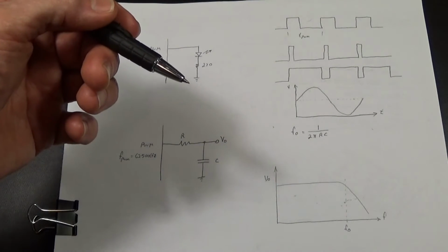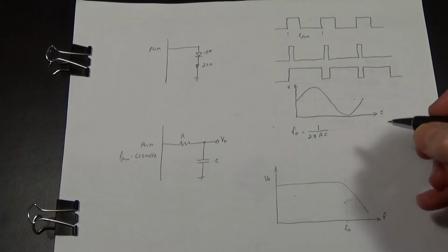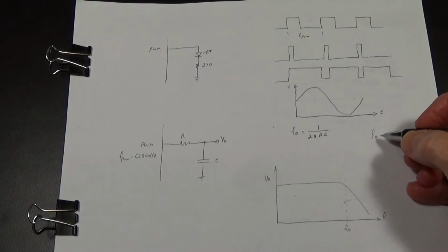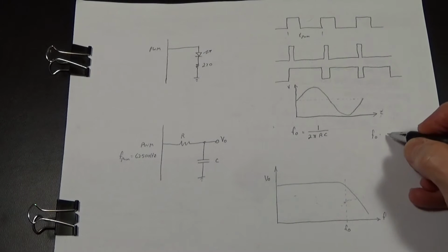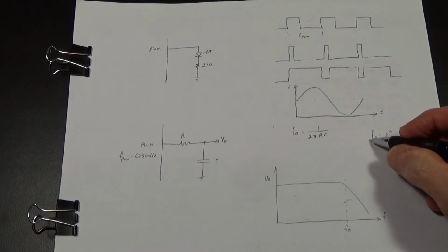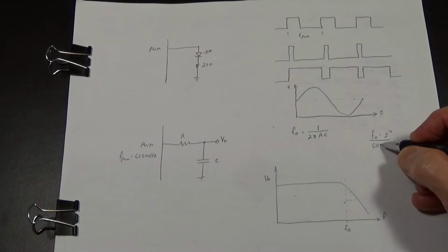You can figure out the frequency you're going to generate with a pretty simple formula. The value that you use to increment your counting register is derived by taking the frequency out that you want and multiplying it by 2 to the 16, which is the 16 bits of our counter, and then dividing it by our update frequency, which is our 50 kilohertz.